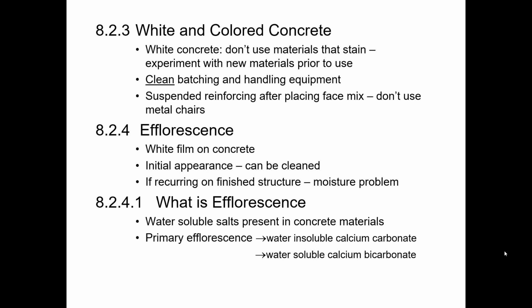All of that can stain that white concrete. You also want to make sure you clean your batching and handling equipment thoroughly, so you don't get any leftover gray or red or green or black concrete from the last architectural mix you batched, getting mixed into that white, because it'll take that color readily, and all of a sudden what might look white to you standing alone, when you put it next to the panel you produced yesterday, may be quite a drastic difference in the overall color.